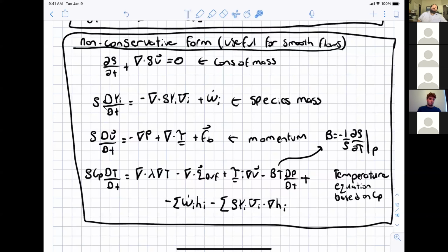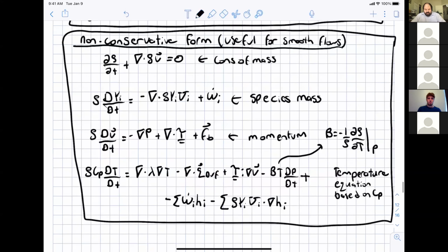Yeah, if you take fluids 1 or fluids 2, like I said, once you get to the non-conservative forms, there are probably literally hundreds, at least a dozen different ways of writing the equations. I just wrote one. Some folks use low Mach number approximations where you work with continuity in this form, but for incompressible flows you would basically use this as your continuity equation.